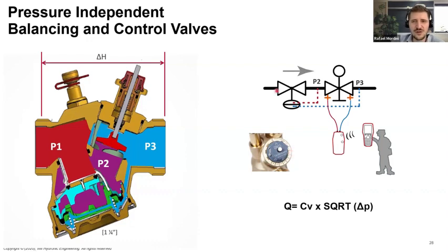You are still able to do balancing on this valve, but those are control valves that in fact do balancing for us. Is there any control valve by itself that can do the balancing? Some people think that the BMS can take over the balancing, which is not true. The BMS is there to vary the capacity of the terminal unit, right? There's just one valve, a new technology out there nowadays, that can do the balancing by itself.